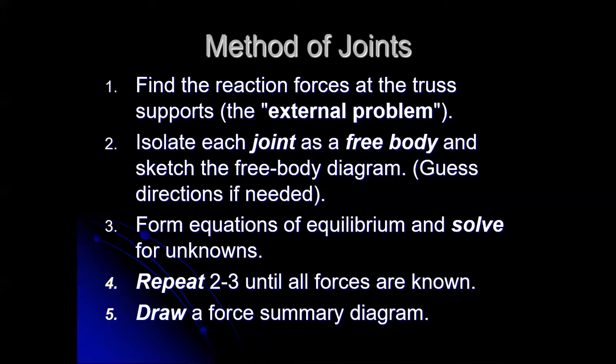If we're not clear which one we're looking at, it can be very difficult to interpret whether something is in tension or compression. People always want to think about the force on the member, but we're solving for the forces on the joints. Those are reflected. They're Newton's third law reaction forces to the forces on the members. So it's backwards. It's counterintuitive.